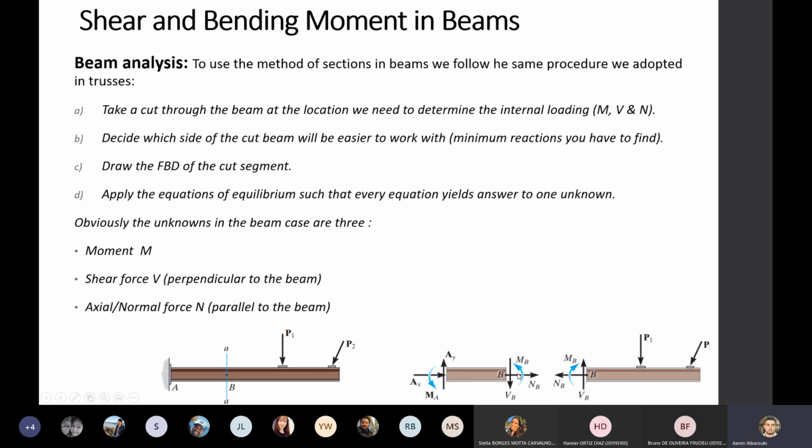If you calculate your reactions, that means you take this part here, because this is a cantilever. In this particular scenario, the same as a cantilever truss, there's a chance you don't need to calculate your reactions. You could have just made the cut and taken this half here. Very similar to the example we looked at. The main difference so far, guys, if you noticed, is that rather than just adding one force there in tension, I've added three: shear force, normal axial forces, and bending moments, because these actions all will be in the beam.